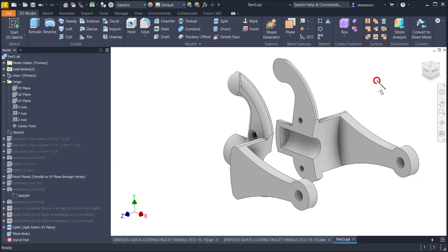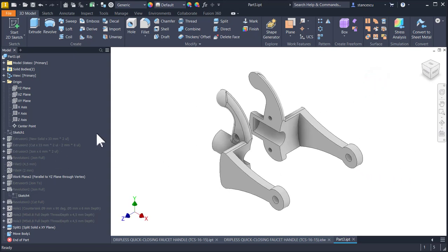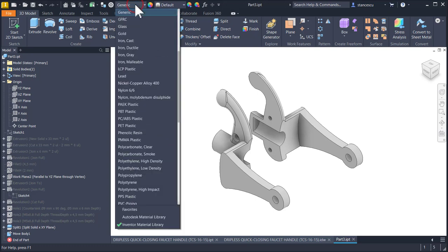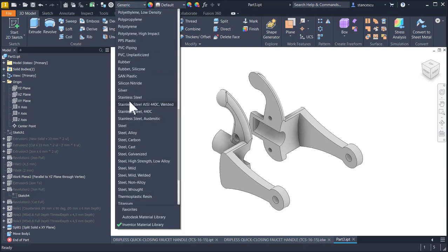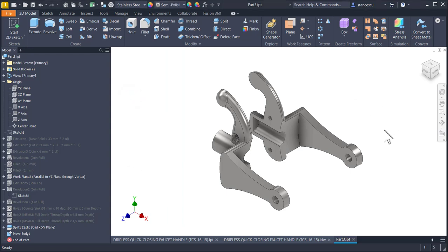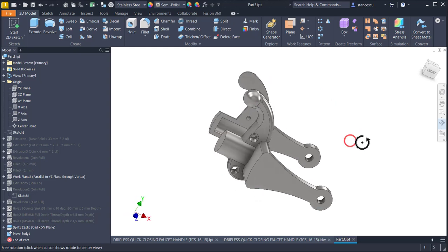Now you see it is another situation. I don't verify the volume, but I apply the material stainless steel. Now you can make a movie with this by selecting this orbit option, going to this horizontal, keeping pressed the shift button, and then apply a small movement.